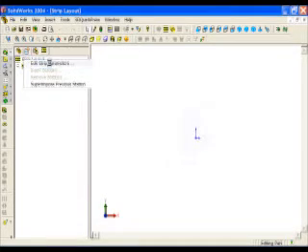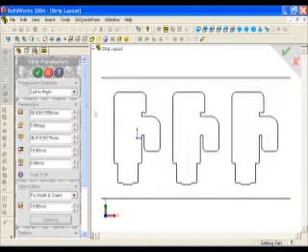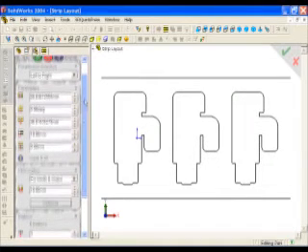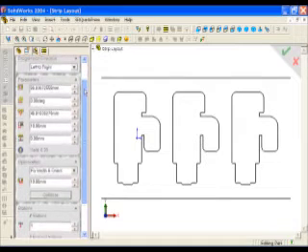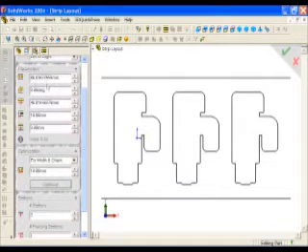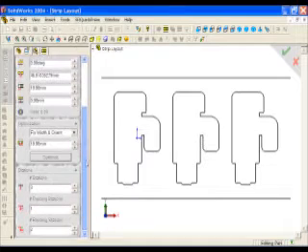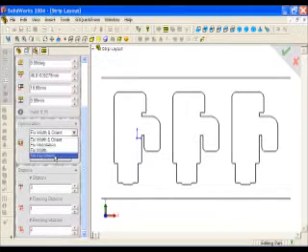Let's go to the parameters of the strip and take a look at the properties on the left. Left to right, right to left for a progression direction. Our parameters, material, angle, and so on. As you'll see here we also have an optimize. Currently our yield is 0.39.